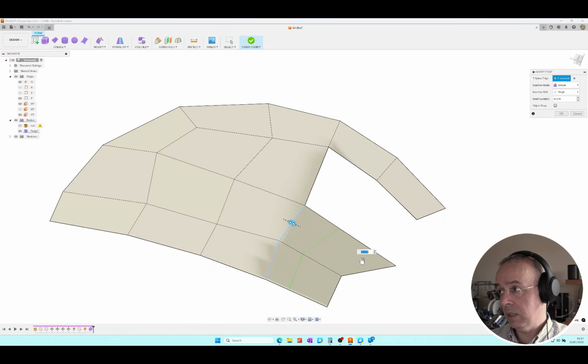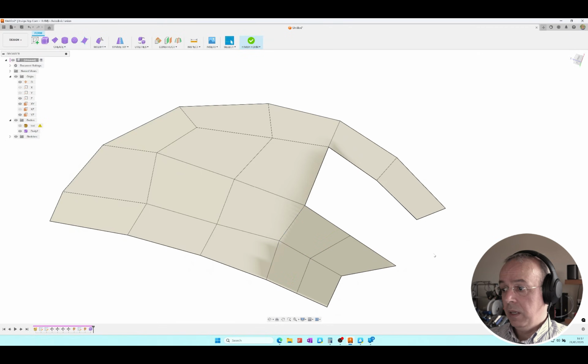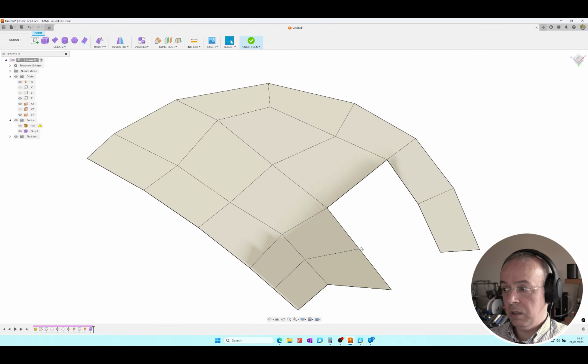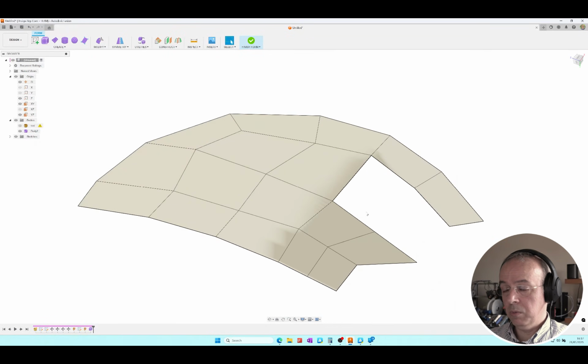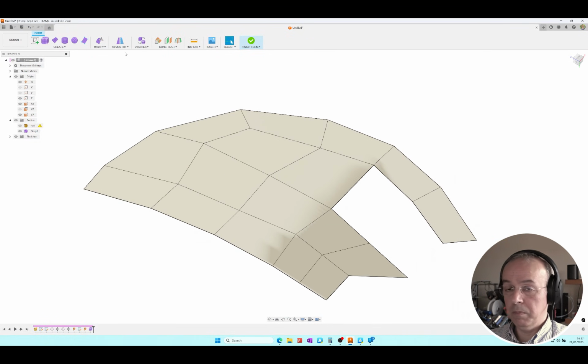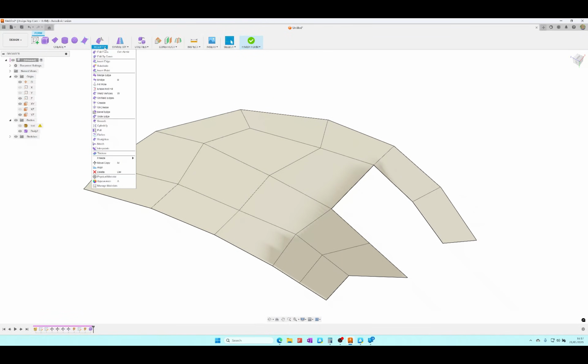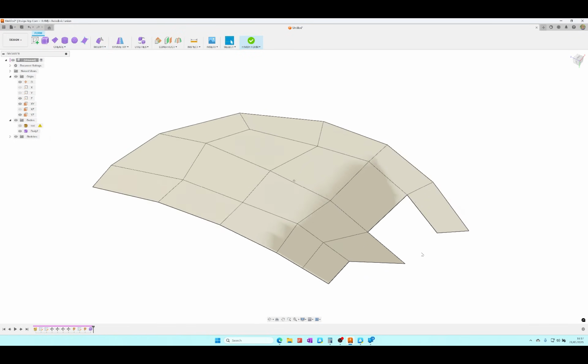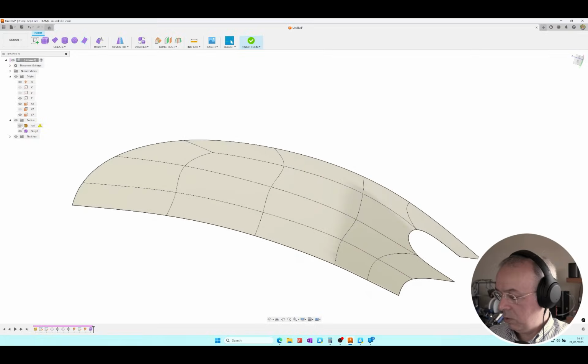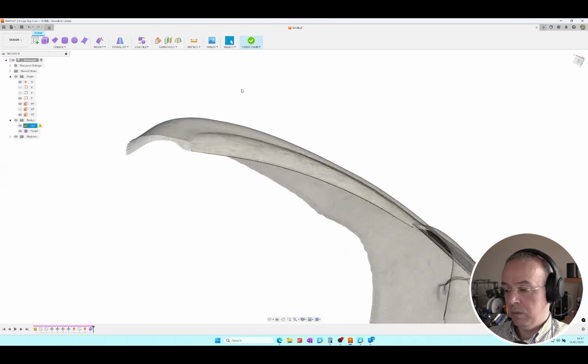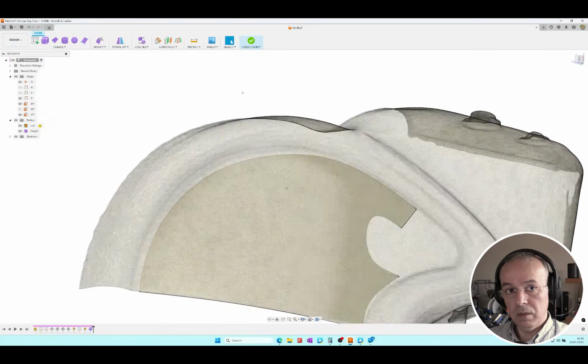In this case, I'll instruct the software to place the division exactly in the middle of the faces immediately below. Therefore, the value to input is -0.5, which means it's at 50% of the length. Now that the conditions have been set, we can use the bridge command to connect the 2 edges. However, as previously mentioned, we could also use the same command we've been using to construct all the other faces. The result will look like this. Notice that the model is now smooth, and the surface appears accurate and consistent with the original model.